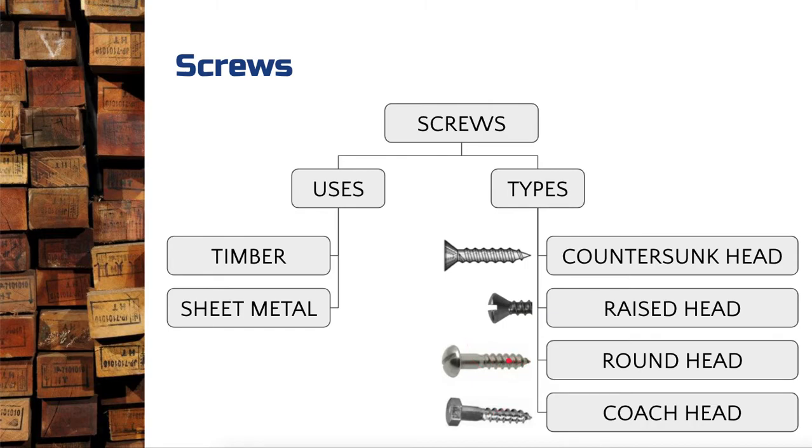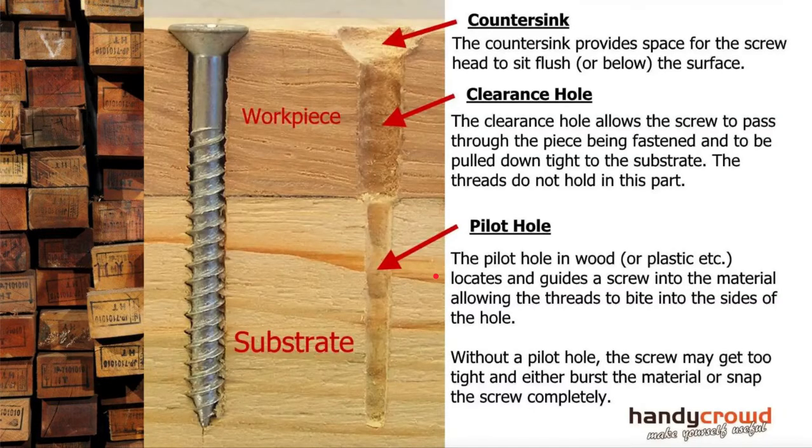Same would go for the round head screws, same sort of application, but usually you're using the round head because it's a little bit more visible and you don't want that ugly hex head. So maybe this would be in bedroom furniture like the frame of a bed or something like that, where you don't want people to be bumping their knees and cutting themselves by running past these screw heads. Raised heads can be used in a whole range of furniture, particularly when it's on show and there's no way around it. Countersunk is when you're trying to actually hide the use of the screw there, or make it look a little bit more seamless with the design.